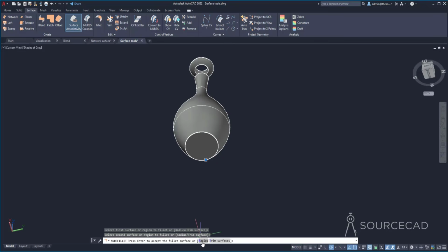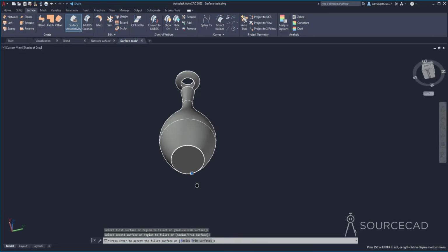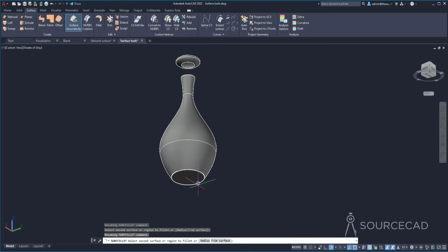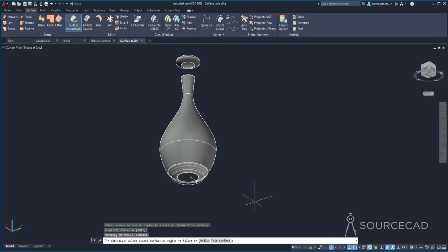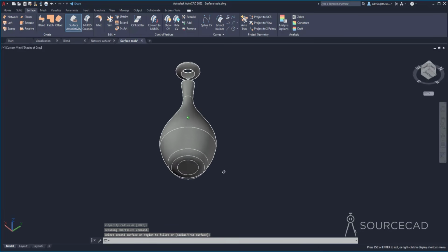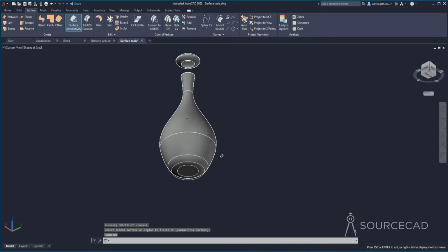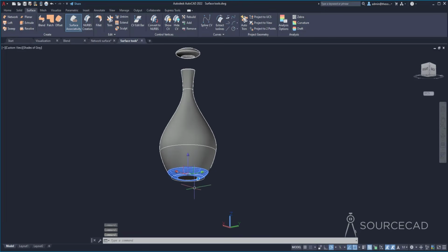So you can click here, specify radius, or if you want to do it manually, you can just select this grip, this tiny one, and just move it inside. If you move it inside, you'll notice that it is adding a fillet. So I'll just eyeball it and I'll simply add a fillet just like this. And I'll press enter and here we are. We've got this flat bottom as well as this fillet, which is added right about here.